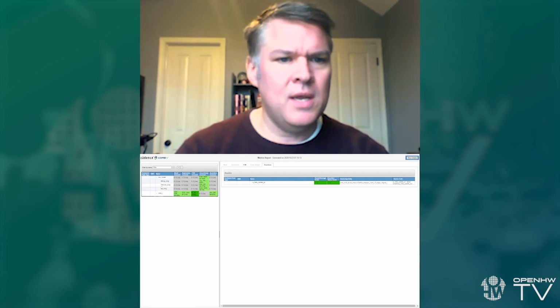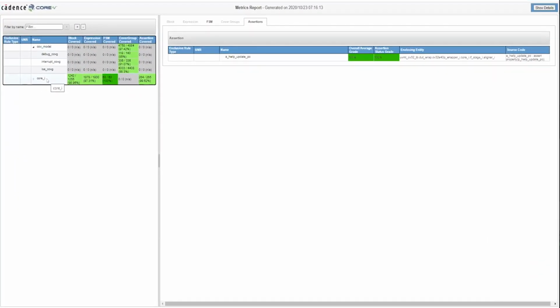Functional coverage, this will be the cover groups using the SystemVerilog covergroup construct. This is really where we're self-defining functional, higher-level coverage of things that we would like to see hit in the processor. Typically for a processor, those would be very much the instruction set architecture.